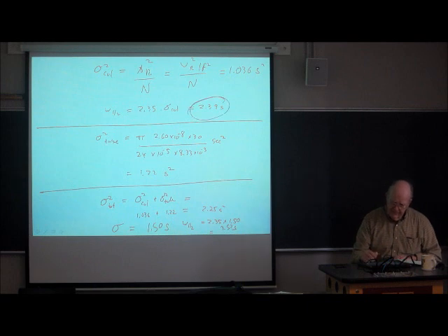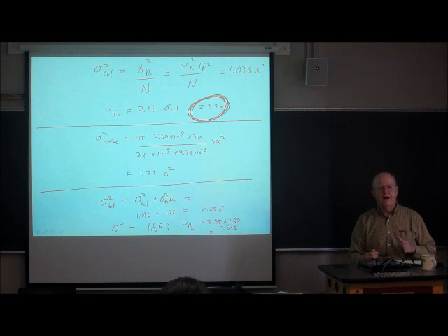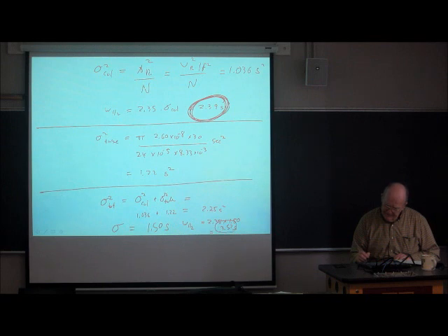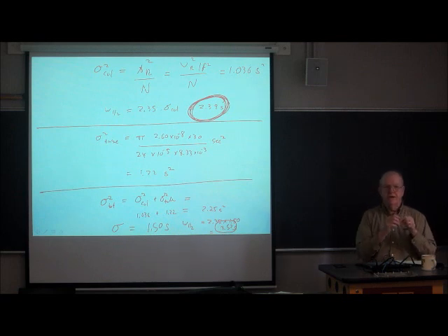So look at this. If you didn't have any connecting tubing, the width of the peak would appear to be 2.39 seconds. Unfortunately, you do have to connect the column to an injector and a detector. And that's going to approximately increase the peak width by 50%. You are going to take a very, very serious hit in the appearance of that peak. It's going to be much wider than it really is. It's going to appear to be much wider than what it really is at the exit of the column.